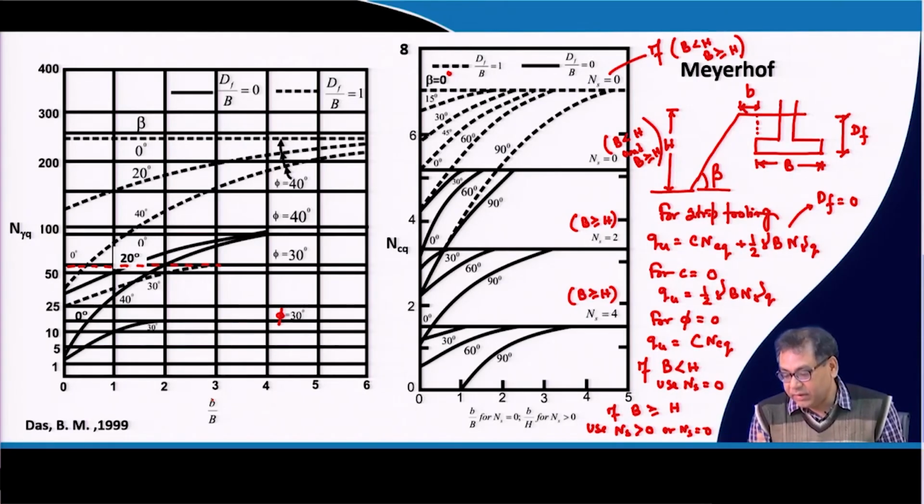Now, if it is for a different footing condition, for suppose rectangular footing, there is no such recommendation given, but you can use those shape factors and multiply with them and you can get the value. Again, as for different cases you can use those factors, those discussed in the previous classes, with this basic equation which is given for the strip footing, and you get the values for different conditions.